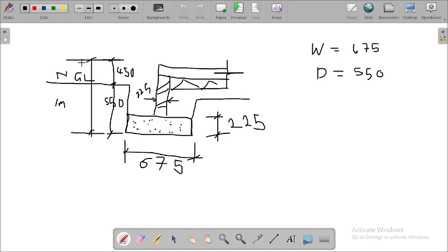Now we said from experience the foundation height is always the total height, that is the height from this point, because this one you have here is your oversite concrete. A layman in Nigeria will refer to it as German floor. This is your oversite concrete.